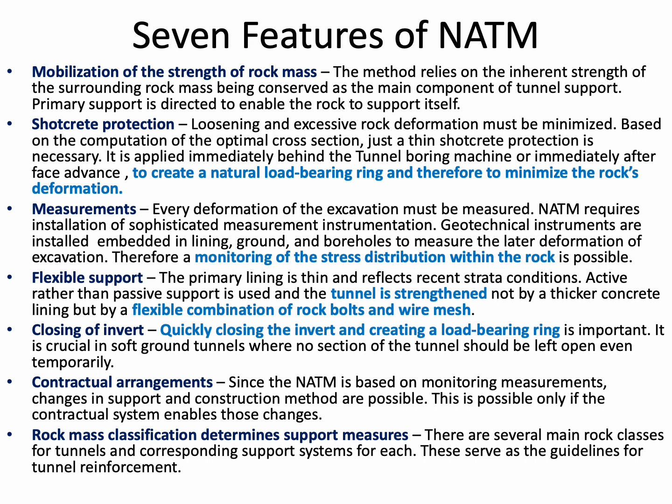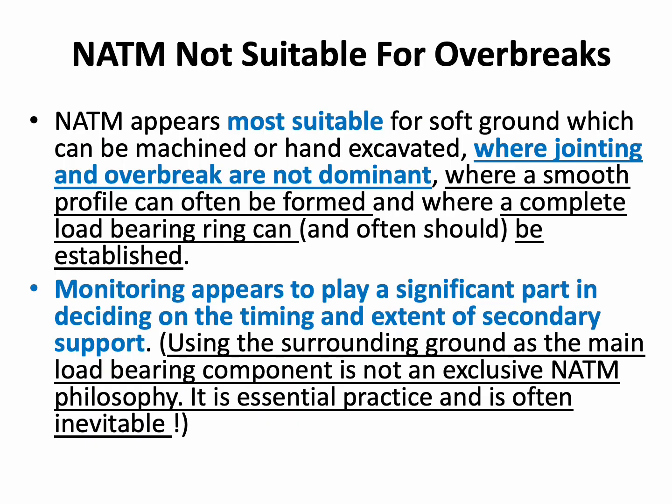Most important is rock mass classification determines support measures. There are several main rock classes for tunnels and corresponding support system for each in NATM. These serve as guidelines for tunnel reinforcement. So NATM is an approach of rock mass classification to determine the support measures. However, it is found that NATM is not suitable for overbreaks in excavation.